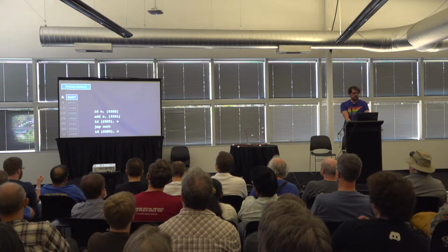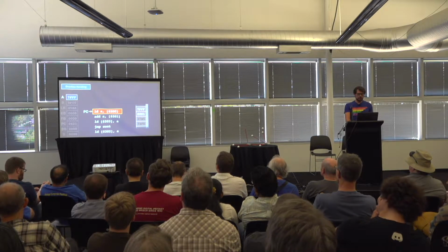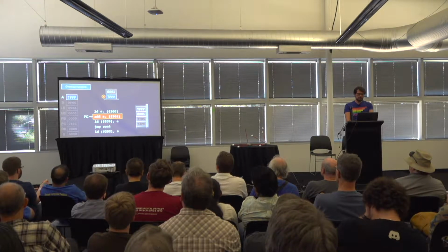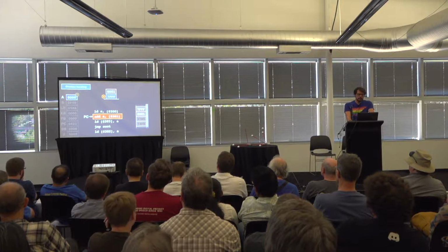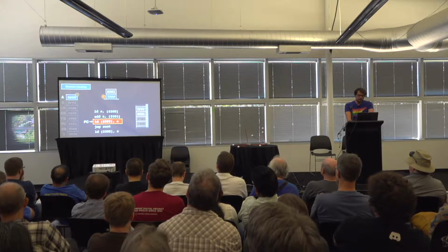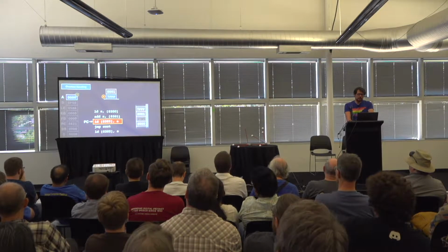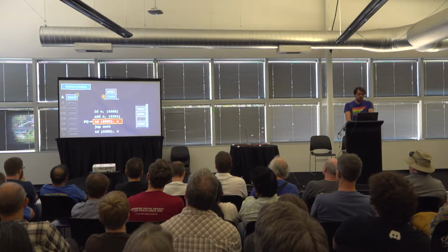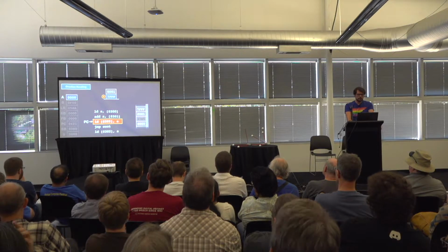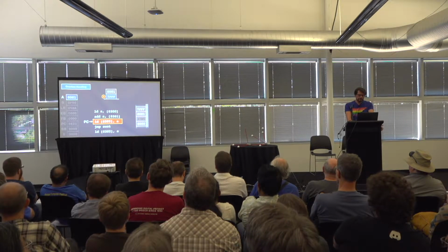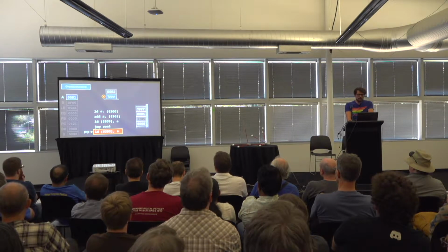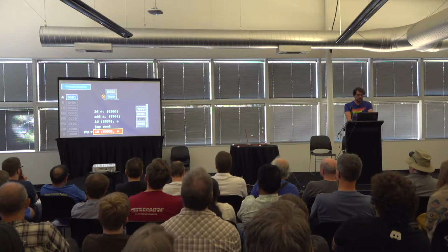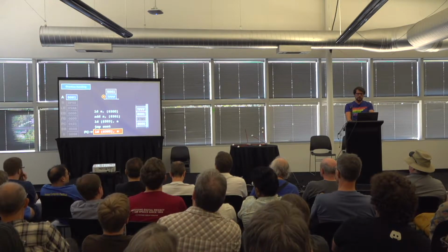So if we have code that reads the value of 7FFF from memory and adds 1, the result is 0 and an overflow is detected, so the accumulator is flagged. The store instruction, in addition to writing A to memory, does extra work if there's an overflow condition. It clears the overflow condition, writes +1 or -1 into A, depending on whether it is a positive or a negative overflow, and skips one instruction. This way, the program can detect an overflow and use the +1 or -1 to apply the signed carry to a higher order word. By storing A to memory, we now have the double word result.